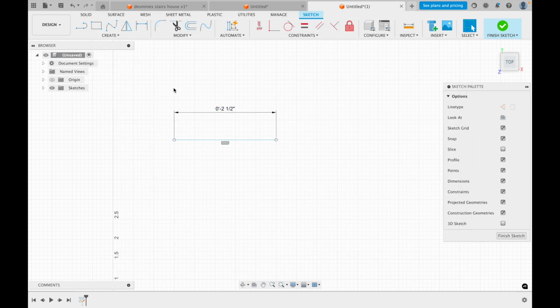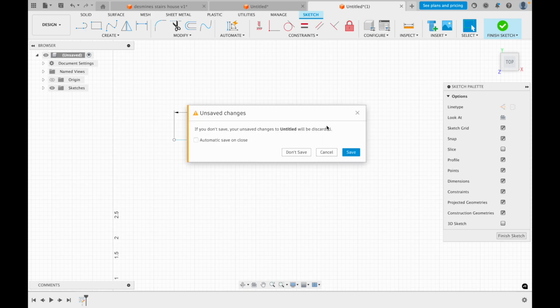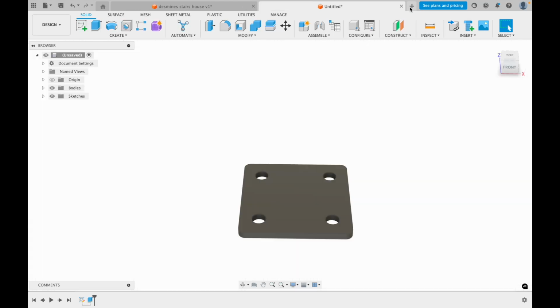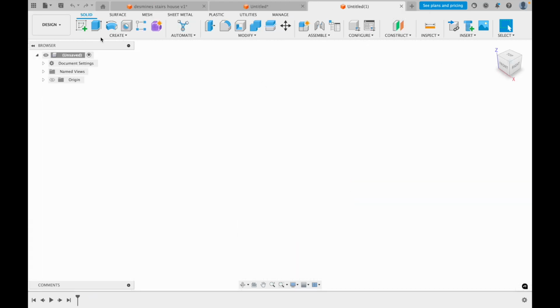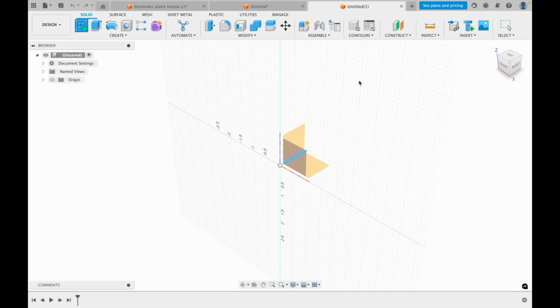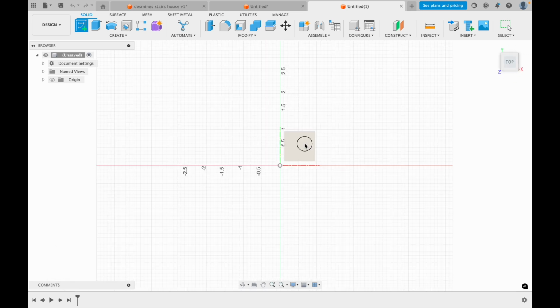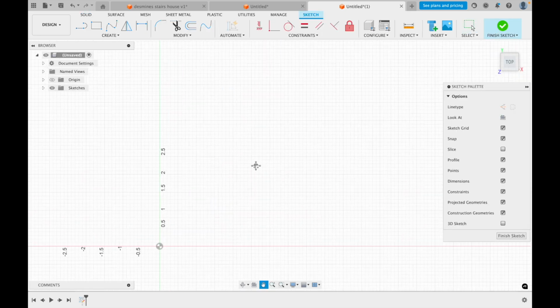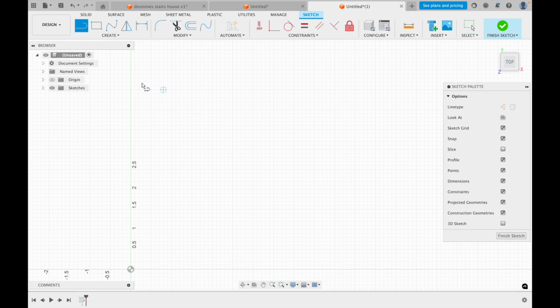And then if you start doing lines, it might still be millimeters. You gotta X out of the whole thing and then open a new page again. Do the create sketch top. And then whenever you do the line again, it will theoretically be back in standard mode, right?